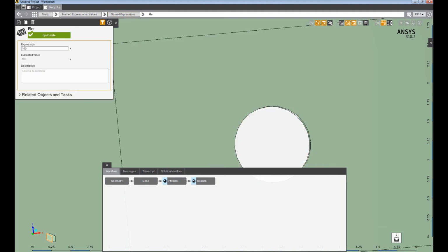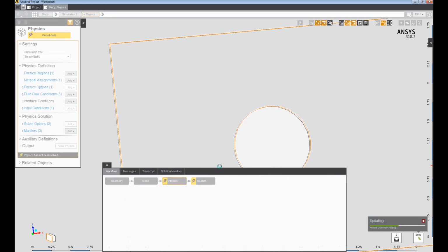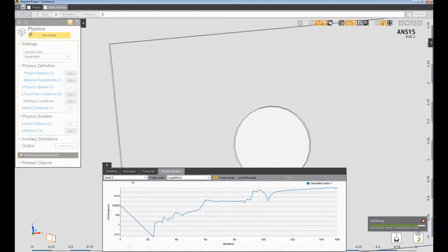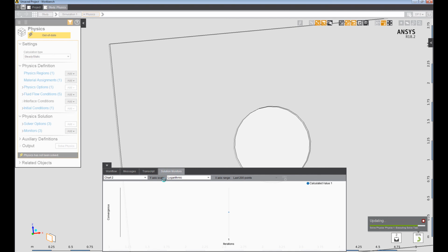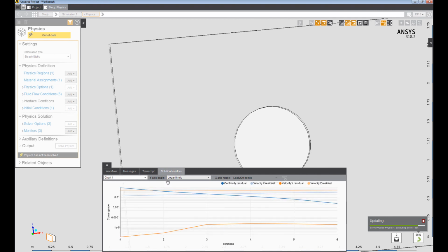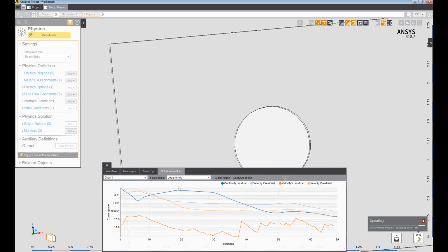We're going to switch this to a higher Reynolds number just to get a converged result. Then we'll switch the turbulence model and see the difference in the results. During the simulation, we can monitor both the convergence residuals as well as the coefficient of drag.